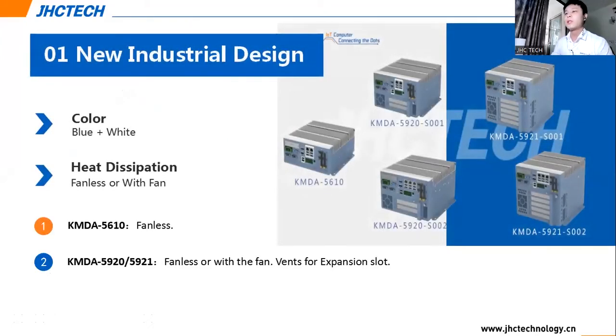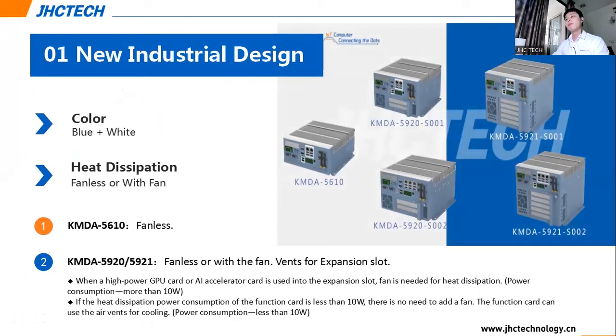Our new KMDA series products are designed to industrial level. The color is blue and white. The KMDA-5610 is a fanless design, and in the KMDA-59 series, because of the expansion slots, you can install a GPU card or other function cards. If your card's power consumption is more than 10 watts, it needs fans for cooling. If your function card's power consumption is less than 10 watts, there's no need for fans because the air vents can be used for cooling.